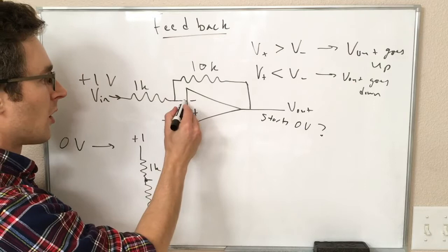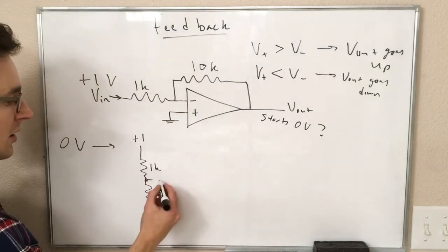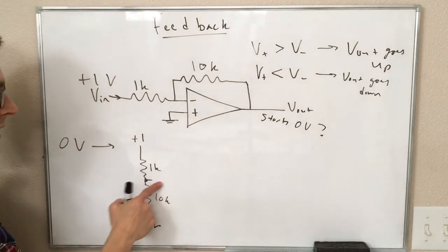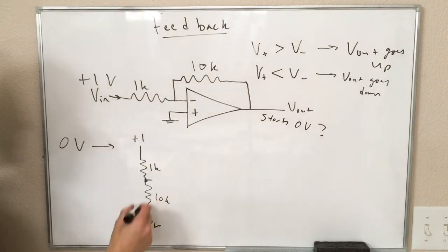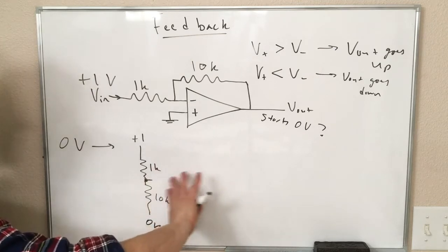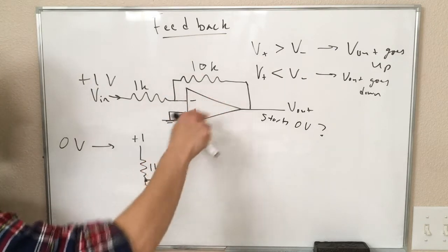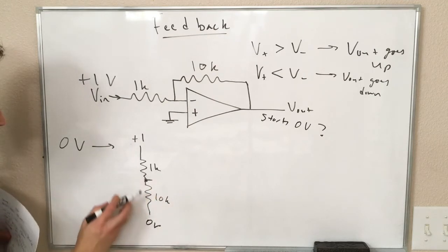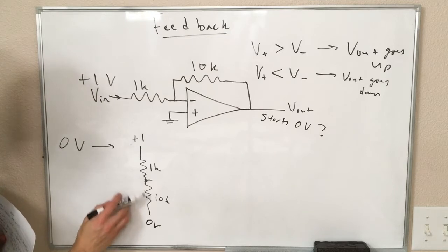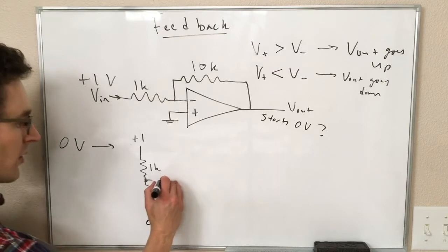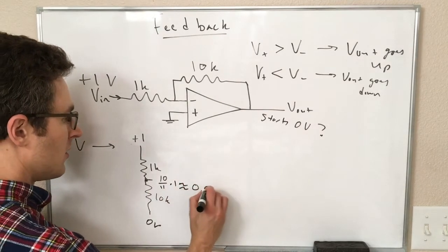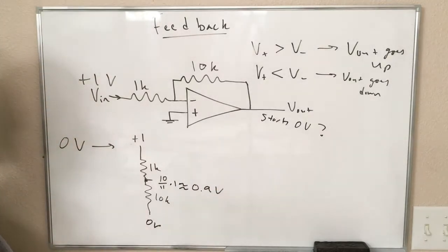So we are going to assume there is no current in or out of this junction, we're not adding or subtracting any current, and that means we can use the voltage divider rule without worrying about anything that's happening over here affecting this. So in other words, the fact that there's no current lets us look at this and say 1 volt, 0 volt. To get this is 10 elevenths, right? 10 plus 1 is 11. So this voltage is 10 elevenths of our 1 volt difference, which is about 0.9 volts.